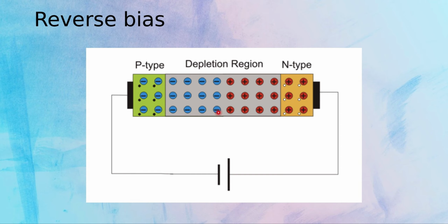Due to the thermal effect, the electrons and holes gain energy and they start to move around the diode. Once they start to move with high energy, they also tend to collide with each other, forming electron-hole pairs. Now, when there are more electron-hole pairs, there are also significantly more charge carriers able to flow and cross this depletion region.